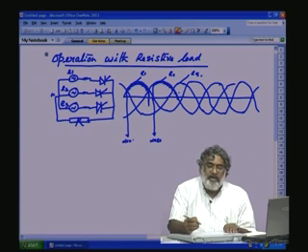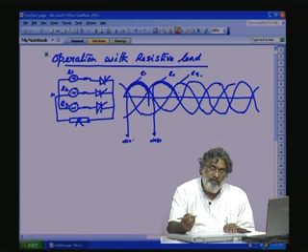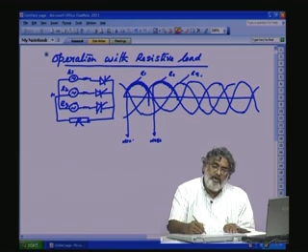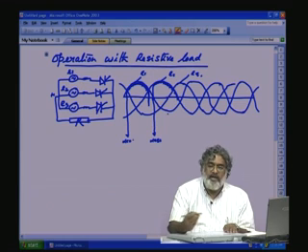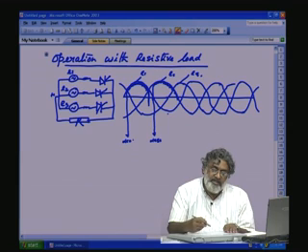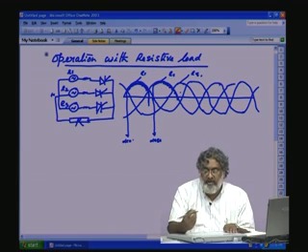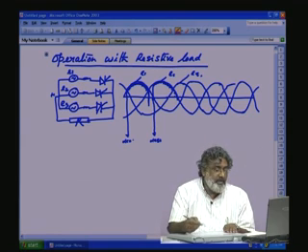So, for resistive load, the current waveform will be in phase with the voltage waveform. If voltage goes slightly negative here, it is not possible, because there is no inductive load. So, the inductive current di/dt cannot change, the slope cannot change, and we cannot force the thyristor in the on state. Here the moment voltage comes to 0, resistive load current will also come to 0, because voltage and current are in phase, and the next thyristor will switch on immediately here. But for voltage control, alpha can go from 0 to 180 degree.